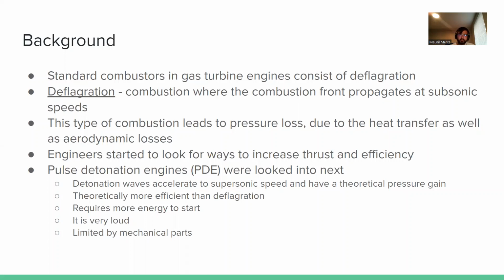One of these methods is a pulse detonation engine, where a detonation wave is created and moves down the channel at supersonic speeds. This wave actually compresses the flow because of its supersonic nature. Thus, this combustion process leads to no pressure losses. Some downsides to this, though, are that it's very loud, it requires more energy to start, and it's limited by mechanical parts. But theoretically, it is more efficient than deflagration.